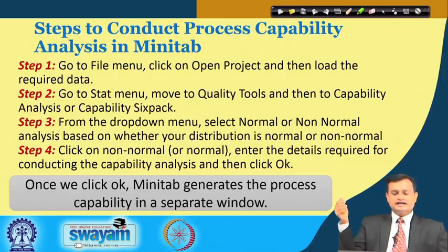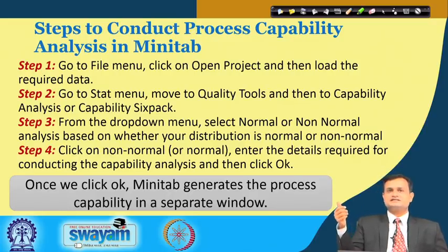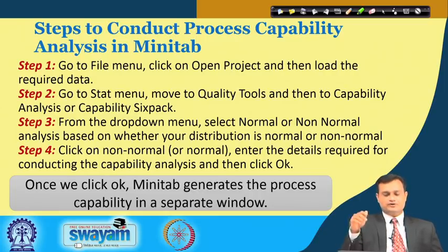Step 4, click on non-normal or normal. For this lecture, as I mentioned, let it be normal. Enter the details required for conducting the capability analysis and click OK, and the moment you click OK, Minitab will generate the various result outputs in a separate window.